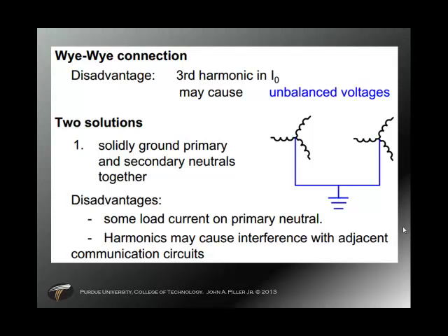What you end up with is if you have third harmonics, and we're going to talk about harmonics. We talked about them in the problems that we have in the power grid. The third harmonic adds up and it adds up on the neutral. Multiples of 3 on the harmonics of the FFT when we use nonlinear loads add up on the neutral.